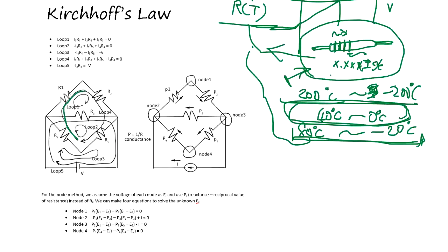Okay, because you take this loop and add up all the voltage along this loop, it comes back, so it's going to be 0, right? And you take this loop, and this equation is made by I in each branch. This is I2, this is I1. So each branch has I and R known. So you solve this linear equation, you can find I.